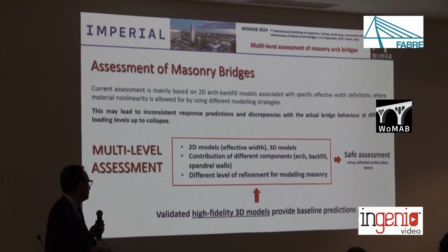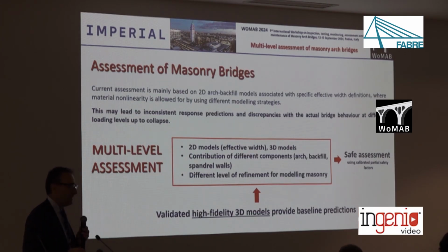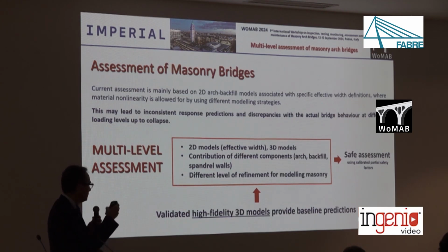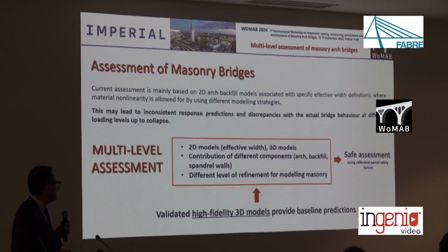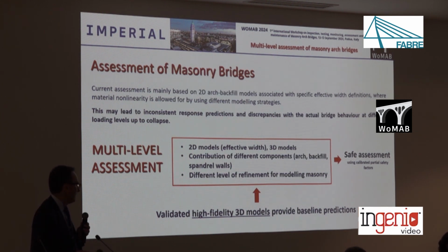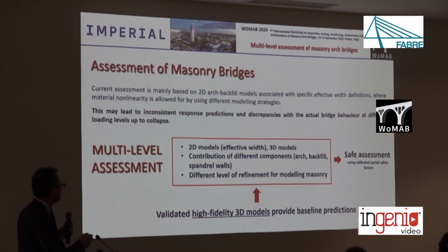And this can be achieved by linking the predictions of simple models to the results one may get using validated high-fidelity models. So the focus here will be on illustrating the potential of using high-fidelity models and how this model can be used to study 3D interactions leading to the complex response of masonry arch bridges, and also can be used to calibrate simpler models.